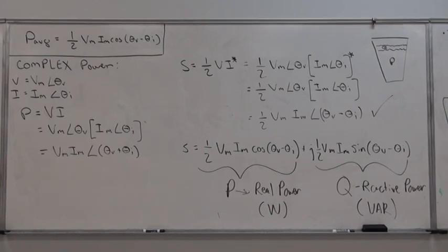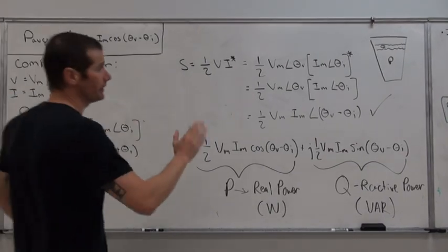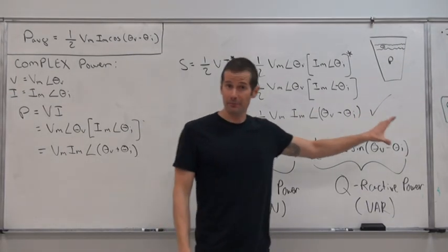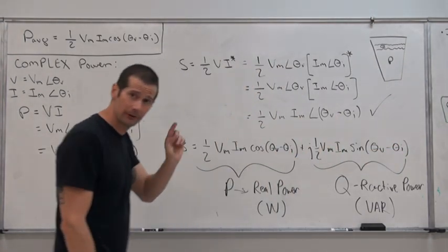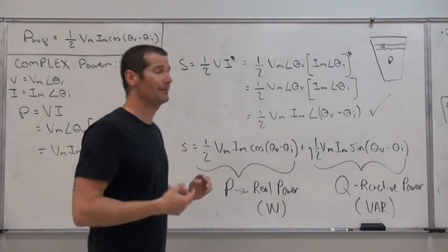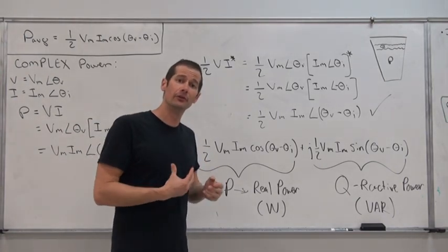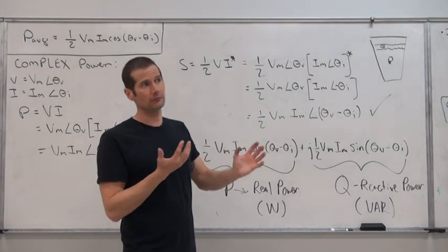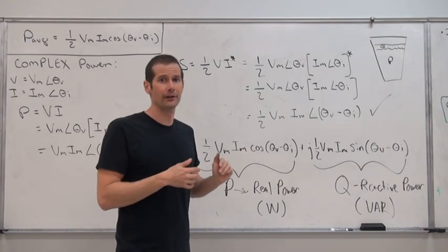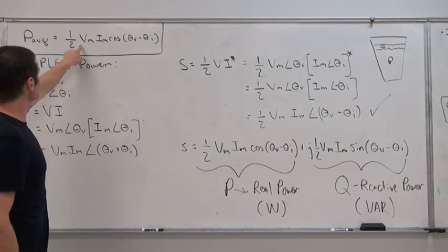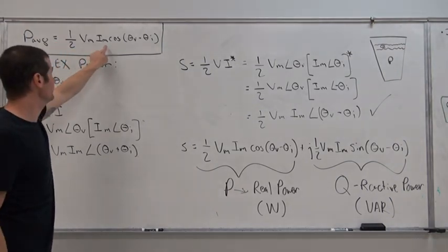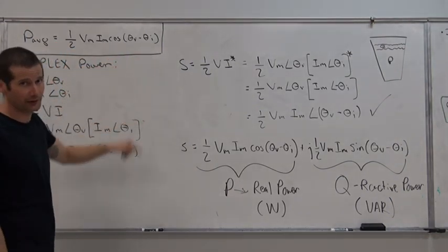So, guys, when we go back and we talk about the average power within the system, that average power is incredibly important to us. And any type of calculation that we do within our system to determine that power always has to map back appropriately to 1/2 VmIm cosine(θv − θi).